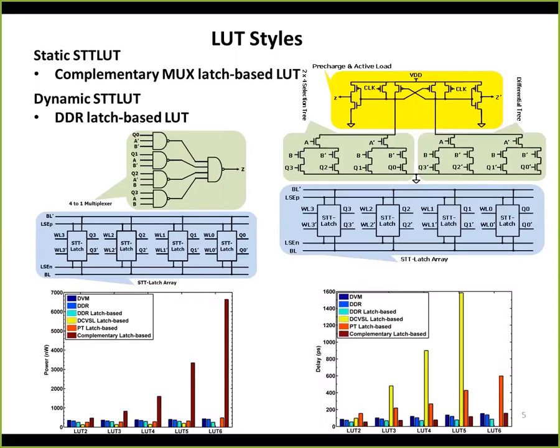You can see the power of the complementary latch-based LUT is much higher than the DDR latch-based one, the blue one right here. And as for delay performance, again, the DDR latch-based LUT has a much lower delay compared to the complementary latch-based LUT. So we expect better performance from the DDR latch-based LUT.